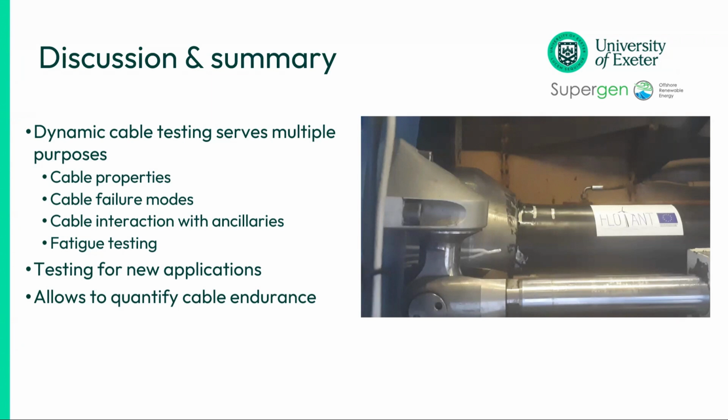What's more effort, and we've done a few of those over the years, is to investigate the different cable failure modes and how they interact with ancillaries. Again, you can do a performance test, and I've showed some of the slides where there's not so much test time involved. Yes, a little bit setting up and running those, but the actual net test can be fairly short. Whereas as soon as you go into fatigue testing of cables, you're looking at 1 million cycles. SIGRA stipulates 1.5 million cycles. So you'd be looking at tens, if not hundreds of days of testing. So that takes a long time. And we've done that for some projects.